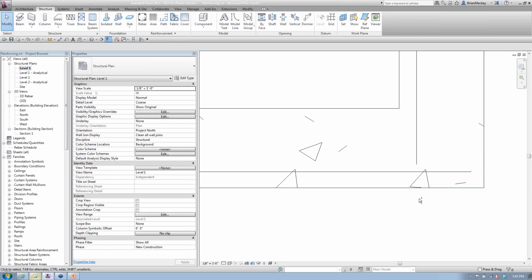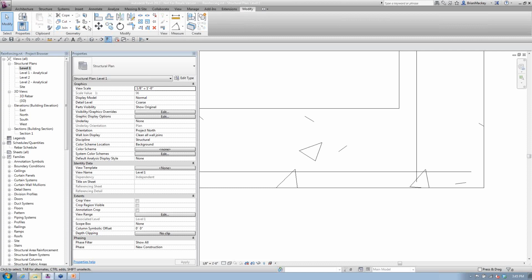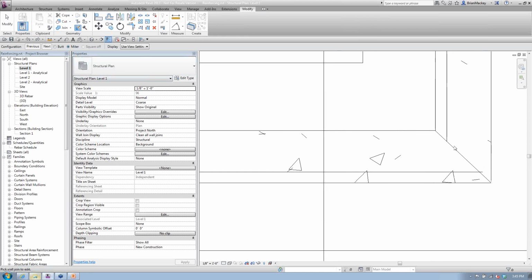The other thing that you can do on that, I'm going to undo that for a second here, is if you really wanted that to happen, I believe doing a wall join edit will fix this as well. So if I come in here and say I'm going to edit the wall joins and pick this join connection here, I believe if you say you want that mitered, it now might possibly pick up on it. So your wall joins will understand that if it's mitered, now I need to stop at the end of the wall because that wall doesn't extend that far.